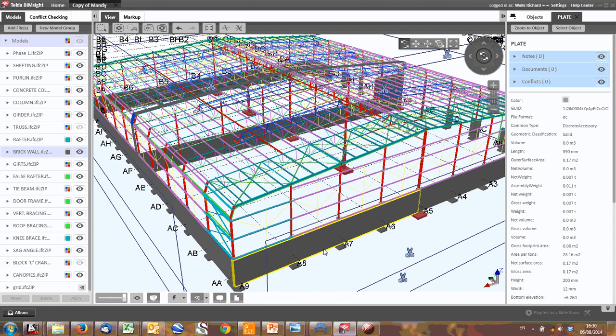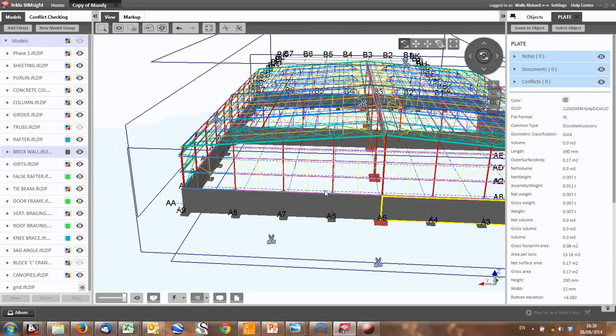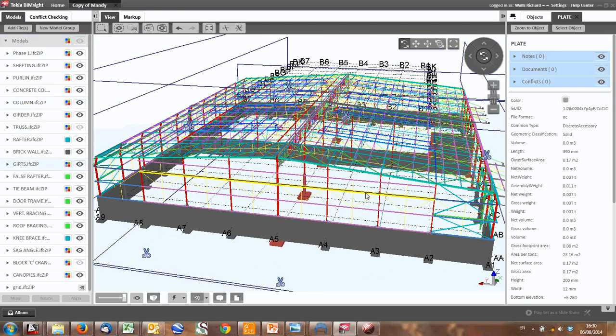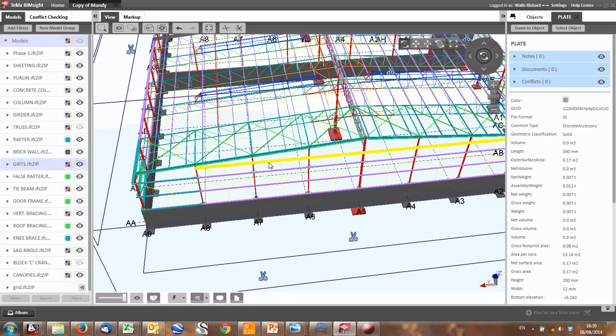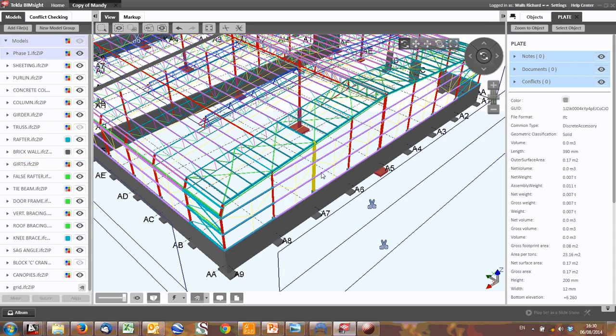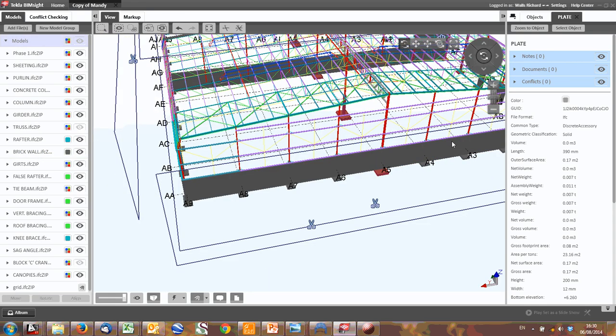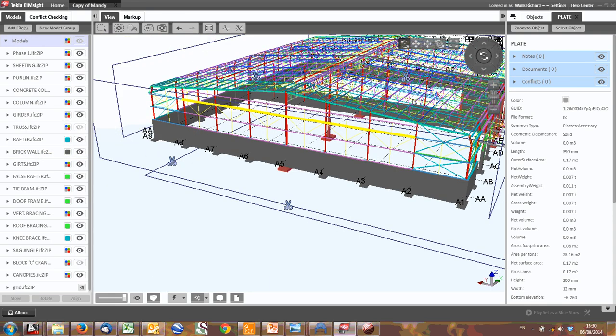And obviously we have our dead load or our permanent load, which is the structure, our live load, which is a variable load, which could be people walking around on top, services, fire extinguishers, pipes in the roof, ducting, all those sorts of things. And wind loads applied to this, and there might be various others that you need to consider, snow loads or earthquake loads, etc. For South Africa, we're not really looking at snow loads or earthquake loads.